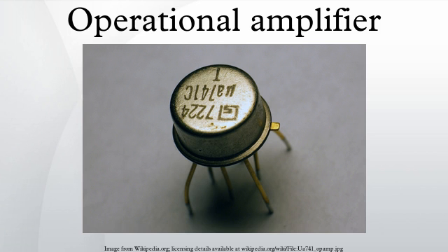Inverting amplifier. In an inverting amplifier, the output voltage changes in an opposite direction to the input voltage. As with the non-inverting amplifier, we start with the gain equation of the op-amp. This time, V- is a function of both Vout and Vin due to the voltage divider formed by RF and RIN. Again, the op-amp input does not apply an appreciable load, so substituting this into the gain equation and solving for Vout, if AOL is very large, this simplifies to -RF/RIN.